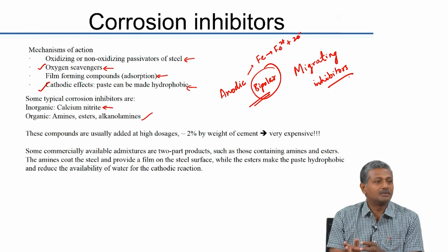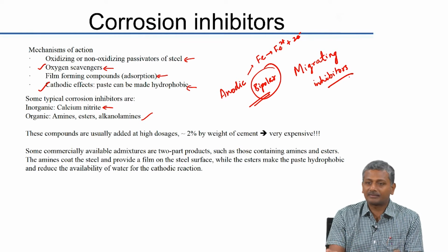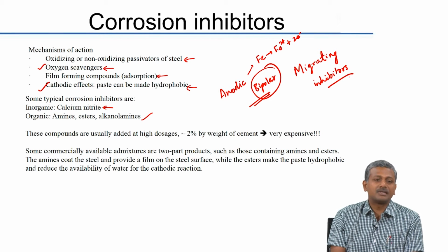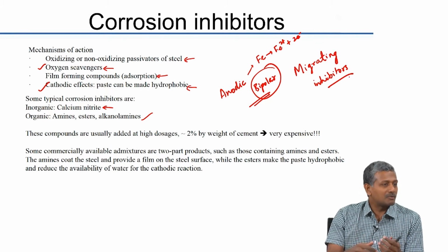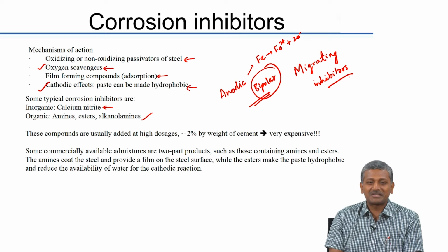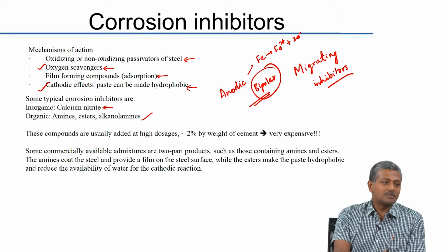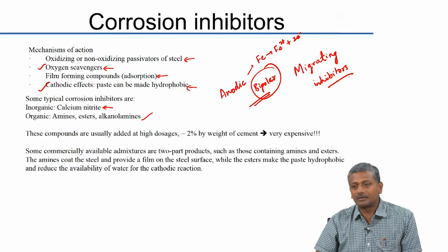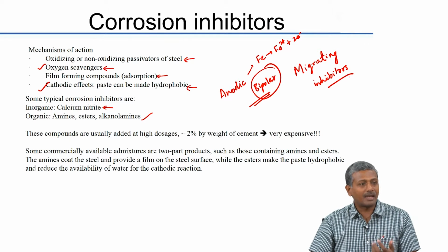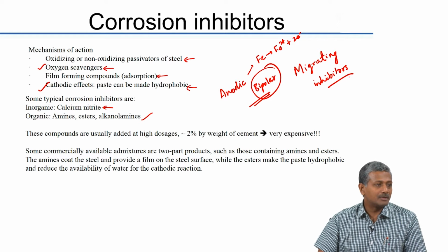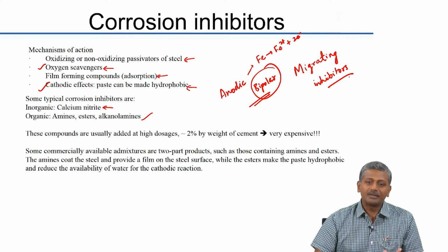People have come to us with this question, how do we test this now, but we go back to them and ask them, okay, how is it that you are using this material? They say that no, we are mixing it with the concrete. Then why are you testing this migrating inhibitor? You should be testing properties of the corrosion resistance brought about by admixed concrete. But unfortunately, the lack of standards and test methods makes it very difficult for us to implement these regulations in practice. So, again this will take some time.